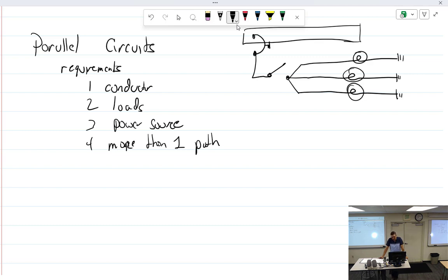If I thought my lights were unusually dim, maybe I have one dim one, what would you do? Bad ground. But what do you mean by bad ground? What is the ground? The hot wires are generally the wires that run to whatever component you have. And the ground wires may be shorter, going directly back to the airframe. Or in the case of a light bulb, maybe the socket is the ground, and that's kind of corroded up, and that's partially part of your ground.